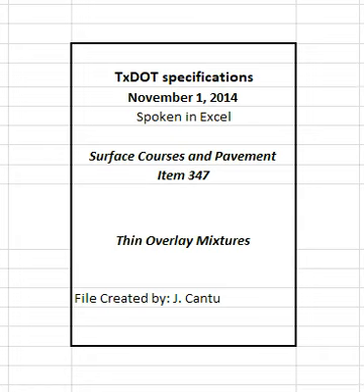4.9.2.4 Operational tolerances. Control the production process within the operational tolerances listed in Table 8. When production is suspended, the engineer will allow production to resume when test results or other information indicates the next mixture produced will be within the operational tolerances.